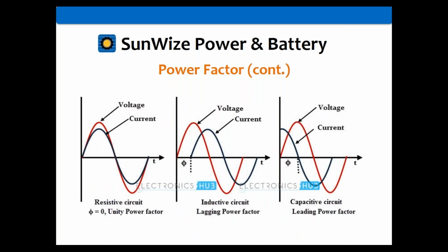Okay, so now, how would this look in the waveform? This, again, comes back to the sine waveforms we already mentioned. So, again, this stuff builds upon itself. You'll notice in the first one, you've got what we call unity power factor, which is basically 1, which means there's no out of phase here. Your phase is 0, which means they're in phase, and you'll notice that your voltage and your current waveforms line up on top of each other.